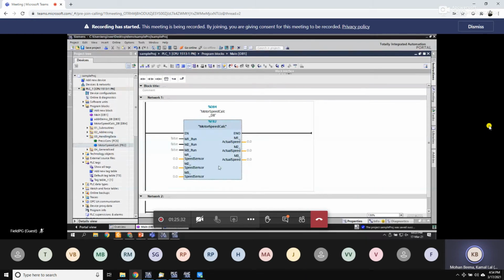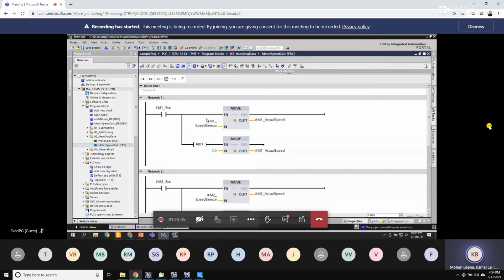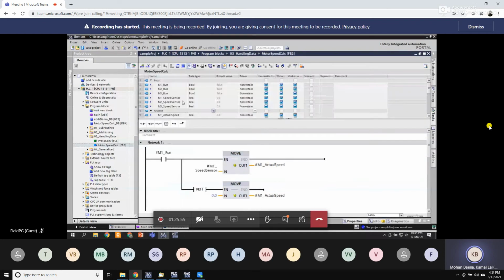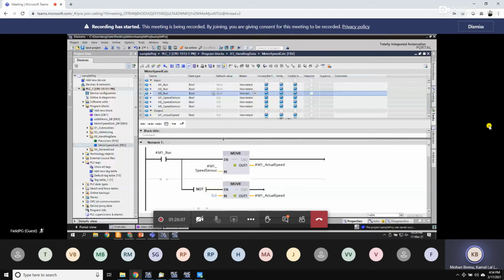Tomorrow I am doing a different project, and in my new project, instead of 3 motors, I now have 7 motors, or I have 10 motors. Now what do I do? I have my logic ready, right? What is the logic required? That is already prepared and readily available. All I have to do is scale it a little bit. So how to do that? I'm not even going to show it manually, but you got the idea. You can copy paste things one by one and make things a mess. Instead of doing all that, let me show you a different way. That's where I'll be using an array.